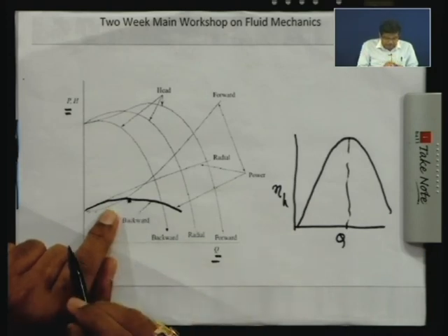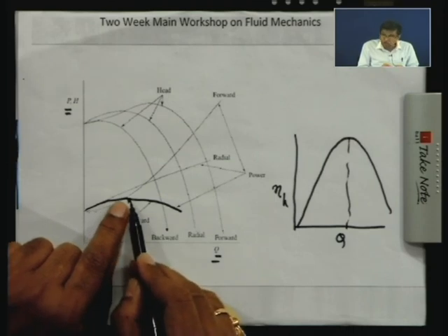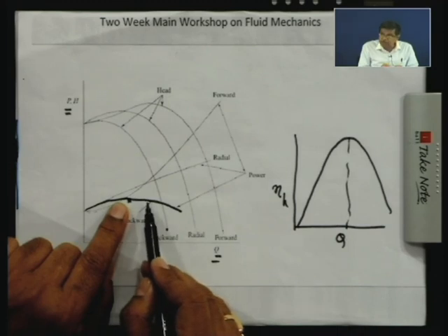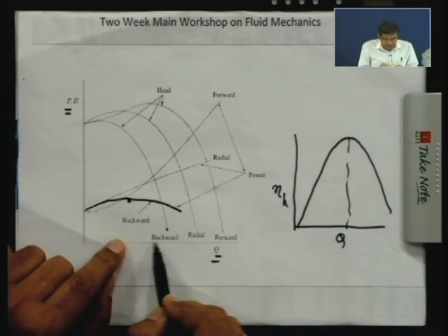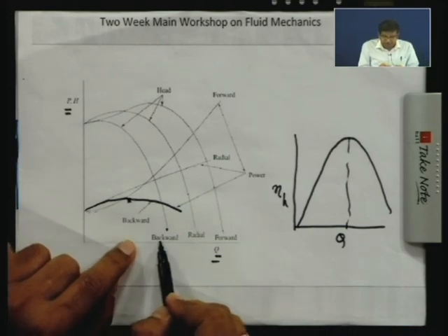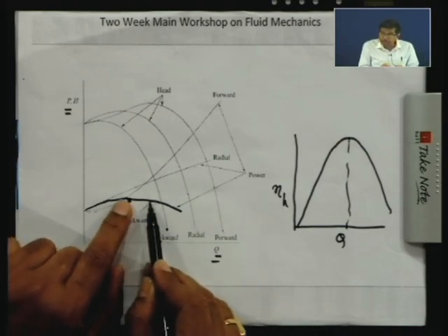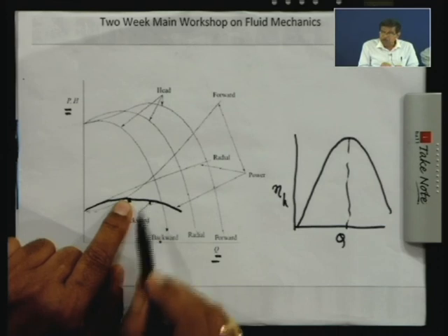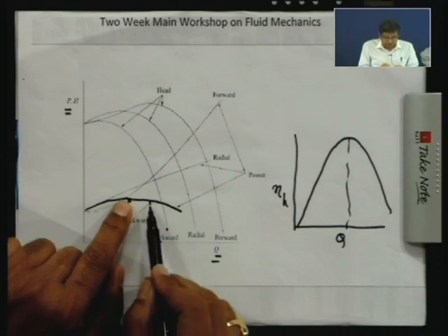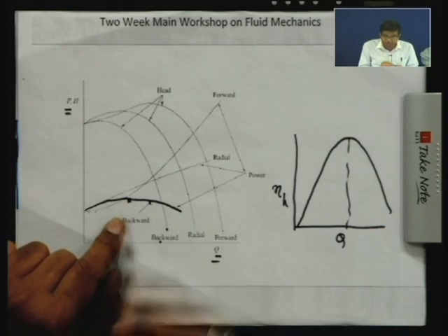Now, if a machine does not operate at the design condition, if it operates at the off design or part load condition, not at the rated condition, then what happens? For example, the flow rate is increased, then what happens? The power is decreased. So, therefore, the motor is safe to be run at this condition. This is known as self-limiting characteristics.